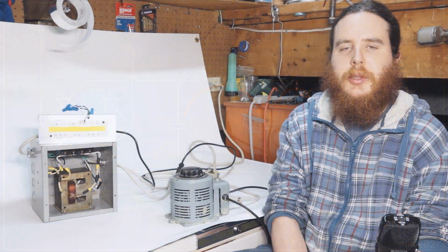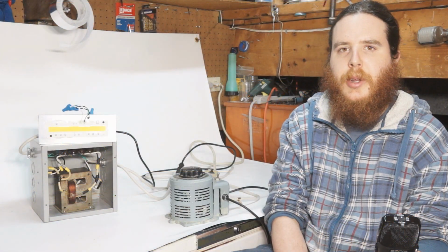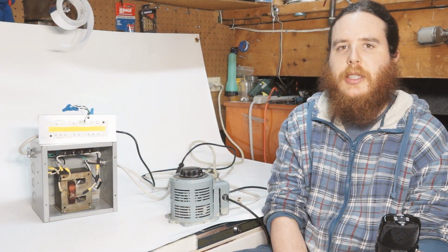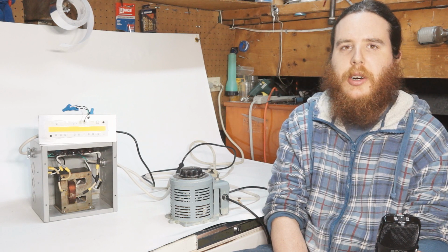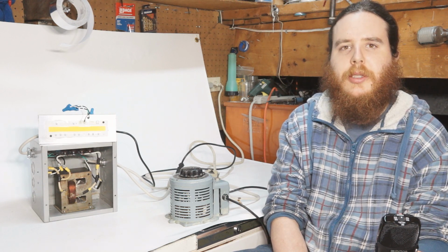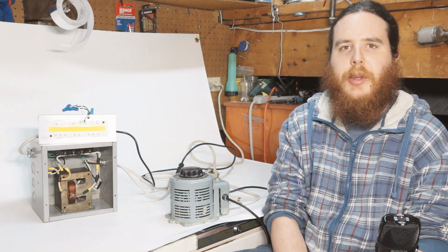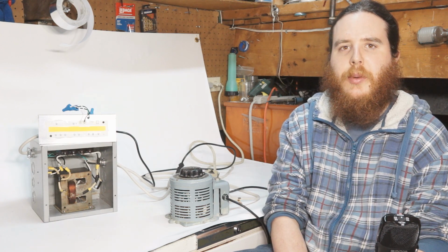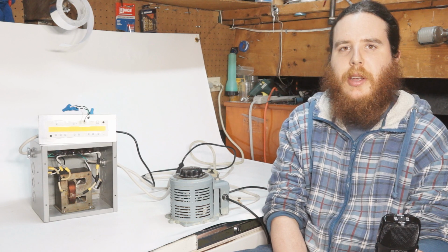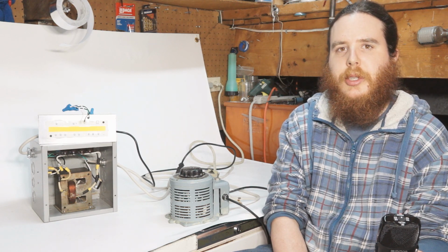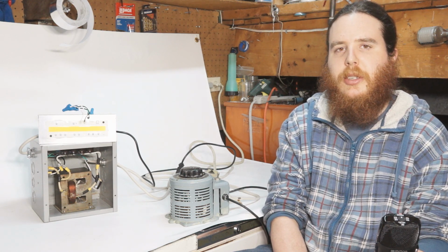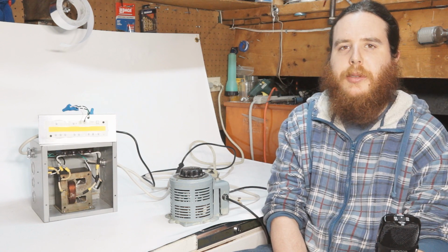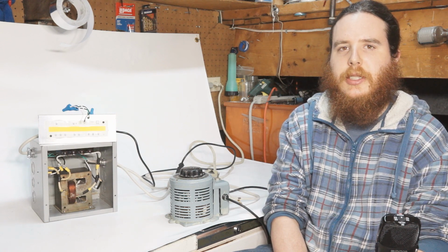There are a couple problems with supplying power this way. The first is that these LEDs are made for 120 volts RMS. RMS, which means root mean squared, can be thought of as if it's the effective DC voltage you're applying when you're using AC. If your RMS AC meter reads 120 volts, it's the equivalent power you would get as if you were using 120 volts DC.